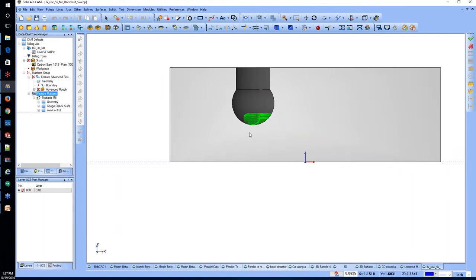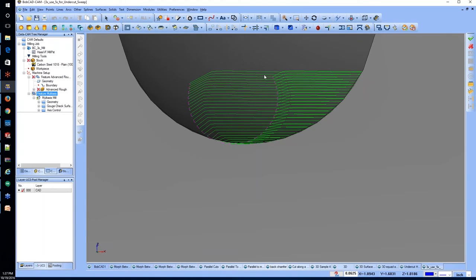And what I'm trying to point out on this is if you look, the toolpath starts out over here over itself, comes down into it, and crosses itself going down. So that's what I talk about when it actually will cross itself. The other 3-axis, like equidistant, you can't get the toolpath to do that because it won't cross itself. It stops the calculation. These ones are actually designed to go back and forth across each other, so that way you can actually get your true undercut out.